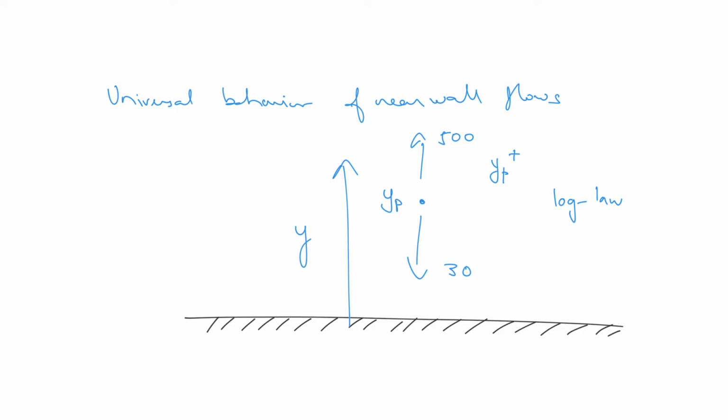The measurements of turbulent kinetic energy, that is TKE, and its budget. You might ask, what is the budget of this TKE? You have this turbulent kinetic energy equation. In that equation, if you find each and every term, that is the production, dissipation, transport, advection, individually, and if you balance them, it is called the turbulent kinetic energy budget.